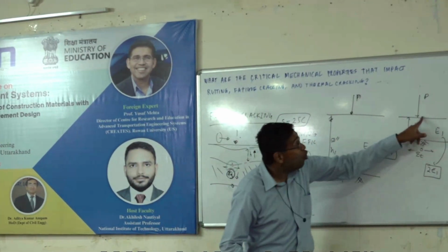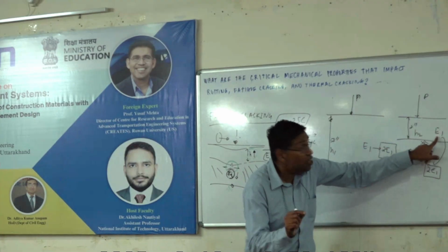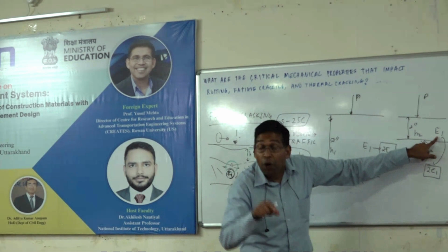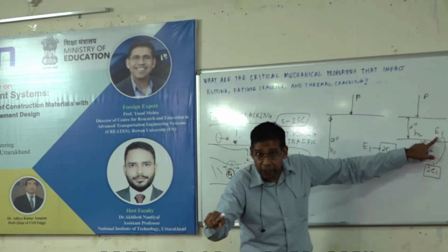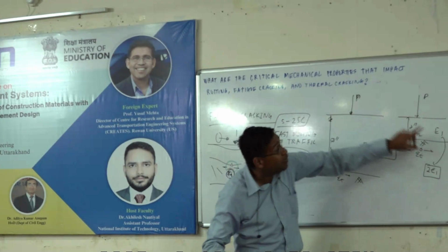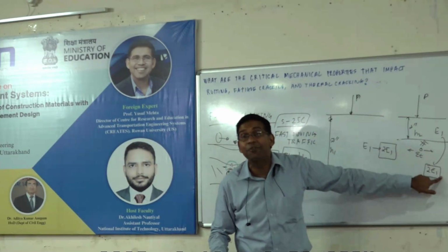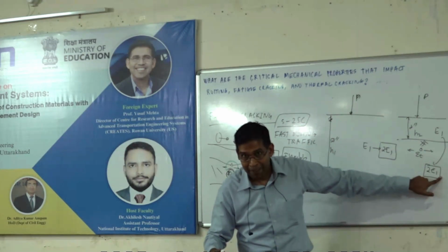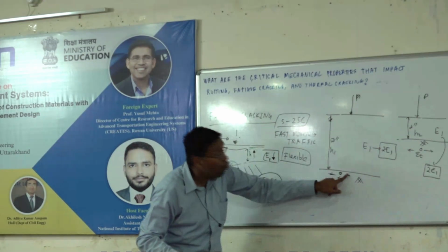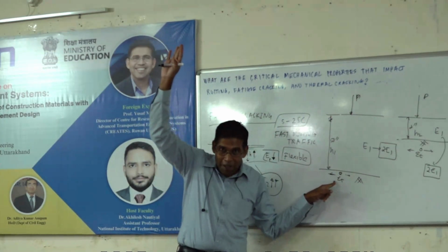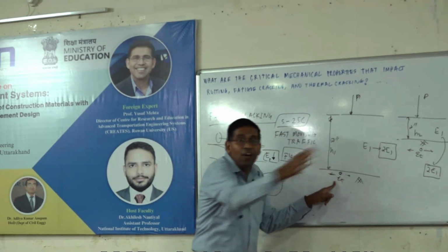But here I'm so close to the load, any investment I make on E1 will matter. I'm answering your question, does it cost? Yes, it does cost, but if I am stuck with 2 inches for whatever reason, it's worth every penny to me to increase E1. I'll make a tremendous impact on epsilon T. Does that make sense? But here I'm so far away. For the epsilon T, my load is so far off that whatever I put here is not going to make an impact.